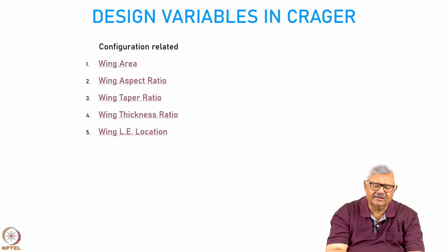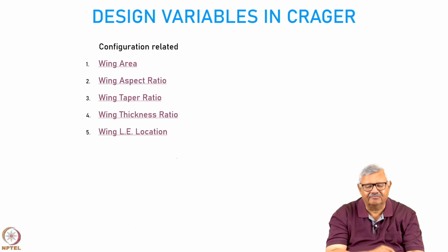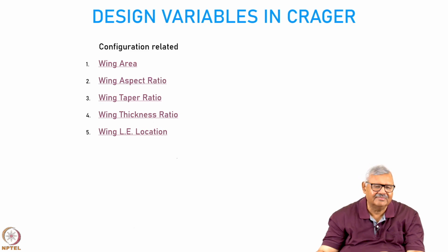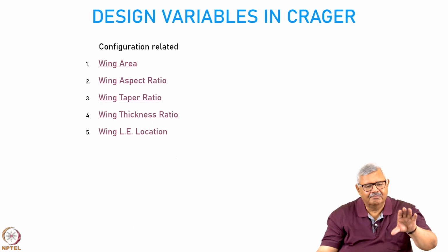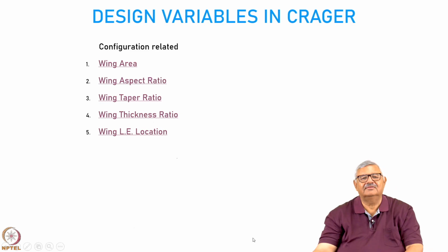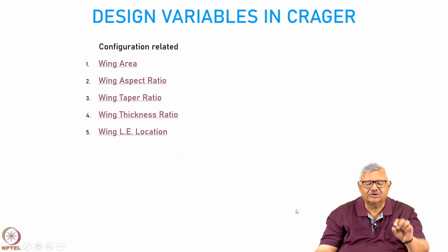A typical wing is going to be around 12% of the total aircraft weight, and that is the one that gives you the lift that you need, and you would like to shape it in such a way that the drag is minimized. So, therefore, a bulk of the parameters, 5 out of 11, are devoted to only the geometry and the features of the wing.